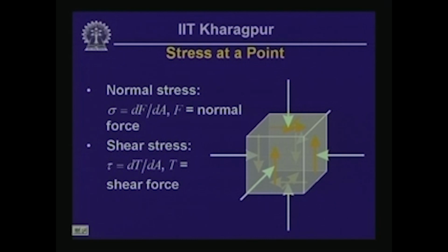And finally, we are going to have four more shear stresses, and now our description of the state of stress of this particular point enclosed by the small infinitesimal cubical element is complete, and what we have here are three components of normal stresses, and what we also have is three more components of shear stresses and their complementary counterparts.